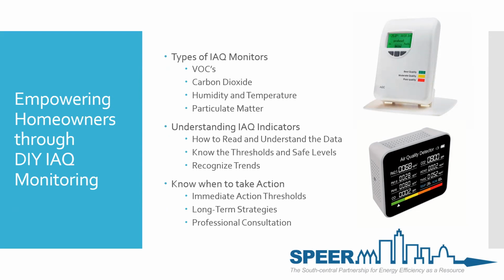Now we'll start plotting things on a chart, and you can see when things get worse. Most people will probably see that indoor air quality will start to diminish over the winter months because you don't open doors that often, you don't open windows, you don't go out as often. So the pollutants start to build. But understanding and interpreting what these indicators are giving you is also key. So read the guide, read the instructions, understand the data that's provided.